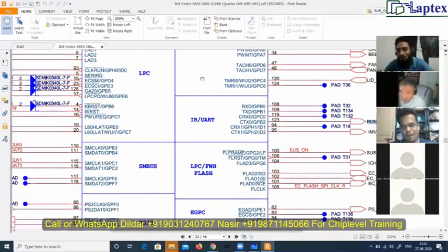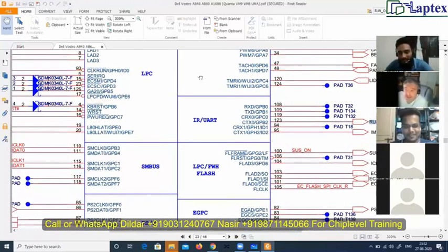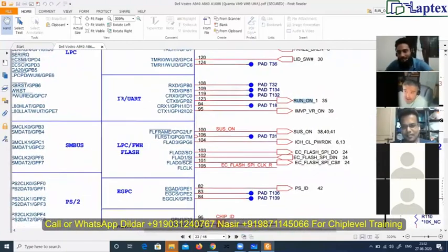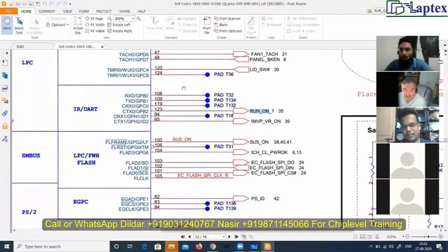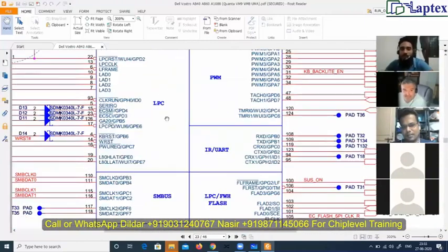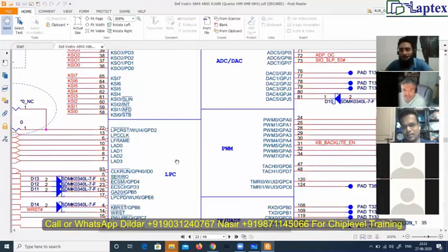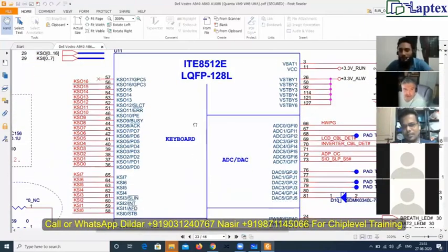Did you put some voltage injection there? Yes, I tried that as well. I cut this supply from here and I put a 3.3 volt supply on this run. But my board was not turning on. Now what do I have to do? What will you do? You return the board, you change the board. Replace two to three IOs.